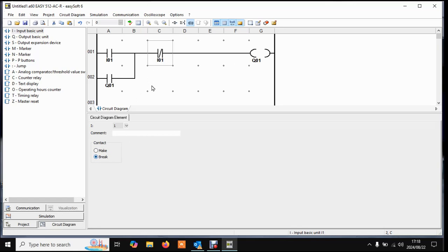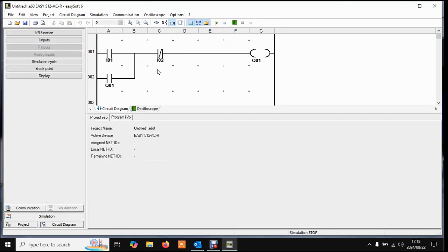We're also going to change the name here, because it will have to be maybe switch number 2, and this one we can leave it as number 1 if we want to, and this number 1. So when we press the start button, the current will run through, switching on that contact, and the circuit will latch on. So now we're going to go to simulation, and we're going to click the play button, and notice it shows us our stop button.